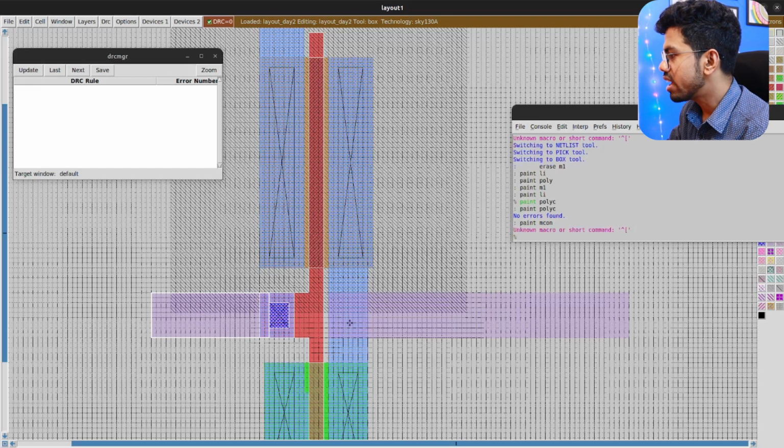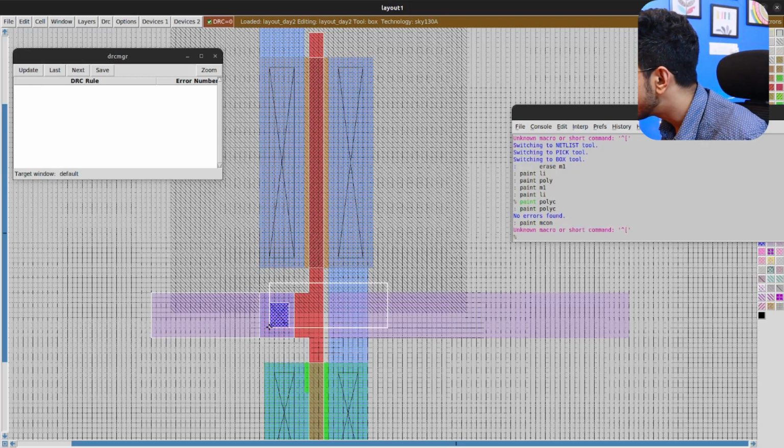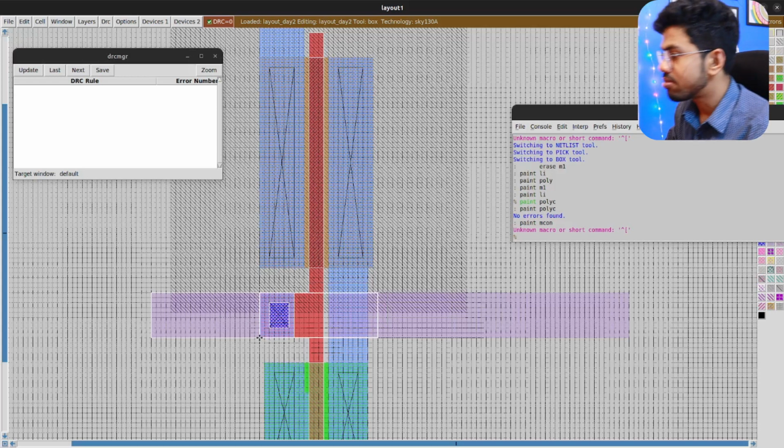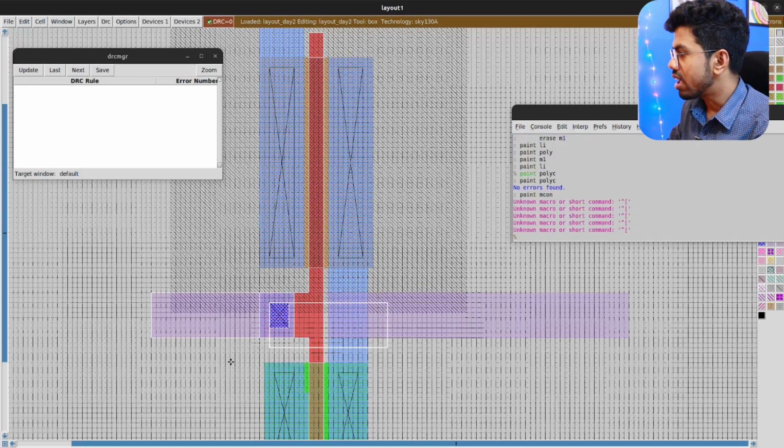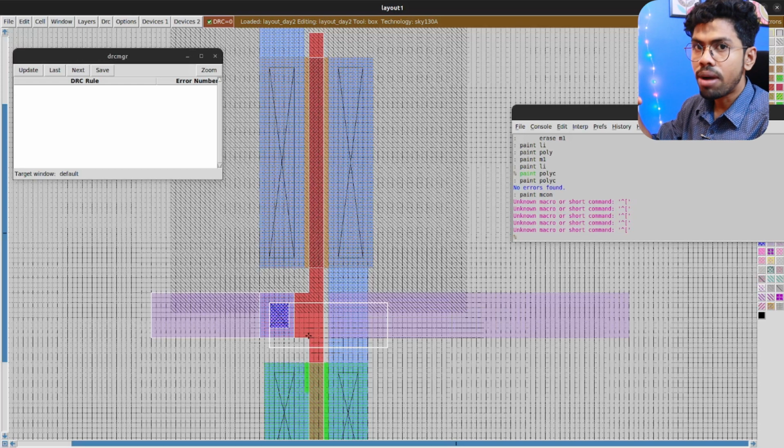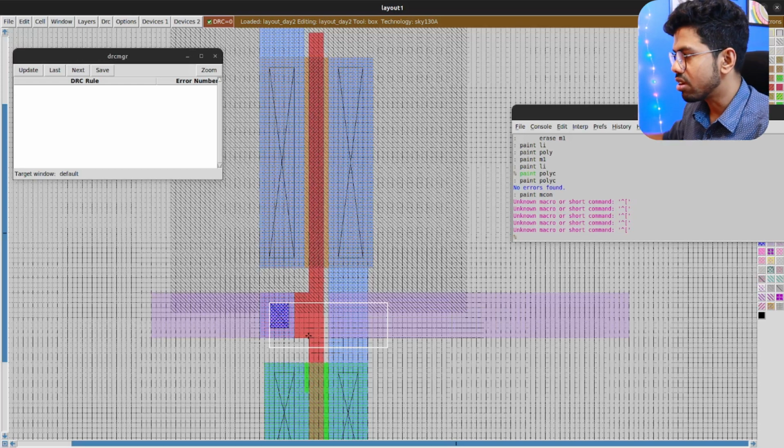Let me select everything here, what I said to you. One thing you can observe is that our selection is still there. I want to get out of my selection. You can see this highlight, right? It got selected, that is showing me the connection. To get out of those selections, you can press comma on your keyboard. So comma and everything is gone.